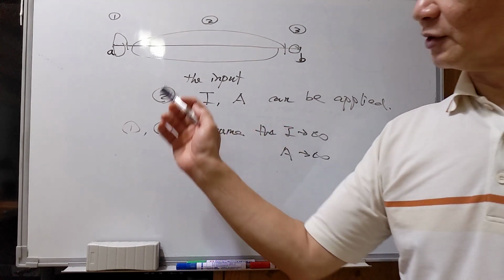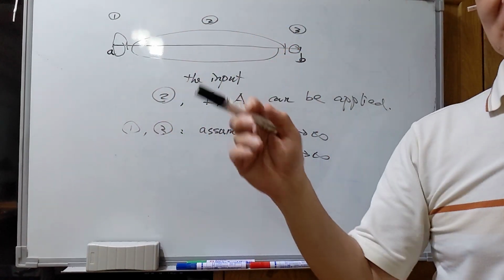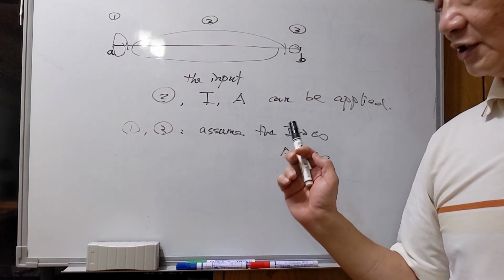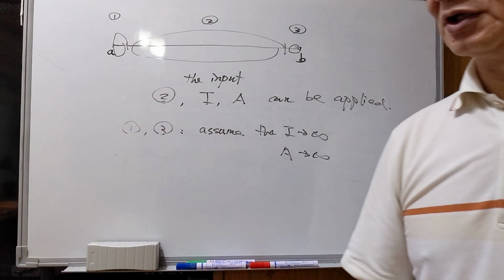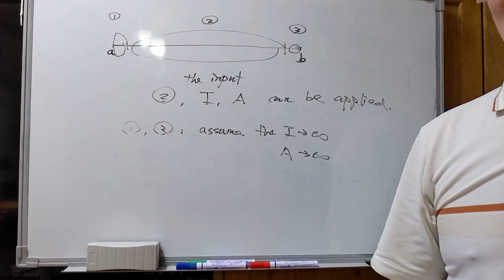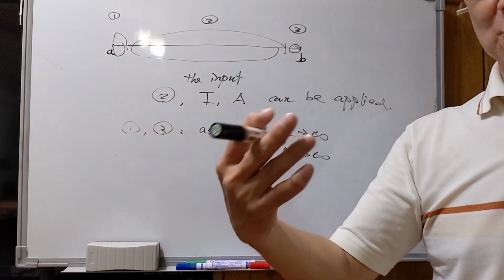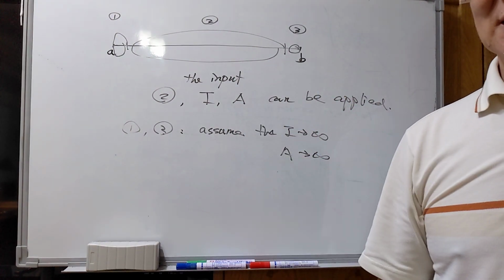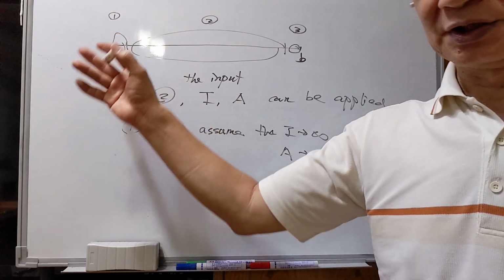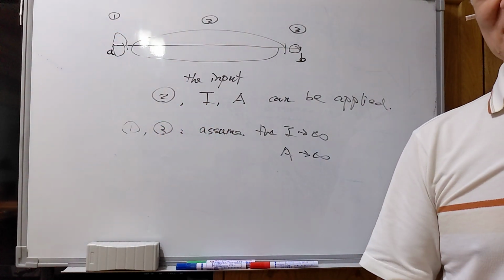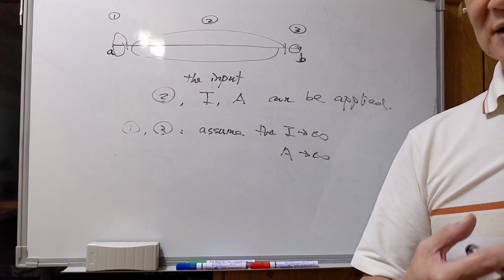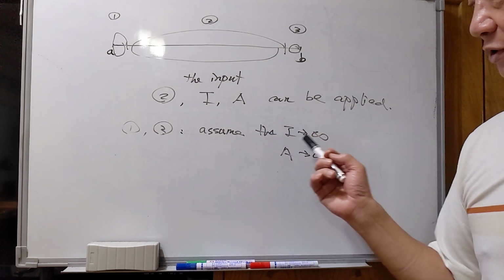For the first and third parts of the element, we assume the moment of inertia close to infinity and the sectional area close to infinity, since we have very large cross sections if you include the part of the columns and the part of the perpendicular beam element. No matter the moment of inertia or the cross-sectional area, they are very large. So in the assumptions, we assume this.